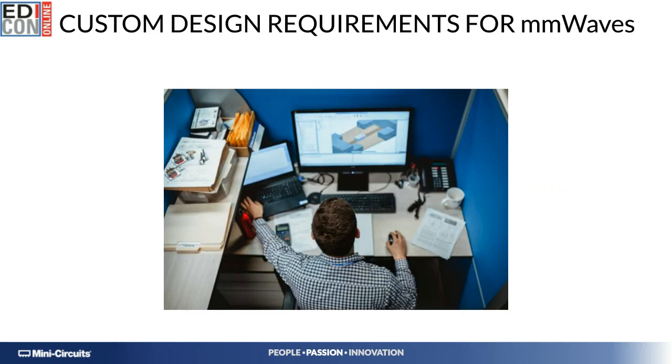One thing we realize is that any work at millimeter waves is truly custom, in the sense that it is almost impossible to employ off-the-shelf parts without having something to be modified. For instance, not everyone uses the same substrates nor thicknesses or multi-layer stack-ups to implement their motherboards. The diversity on these requires a close attention to the way a filter will be interfaced with its motherboard. It requires careful design of launches and interfaces to other surrounding components.